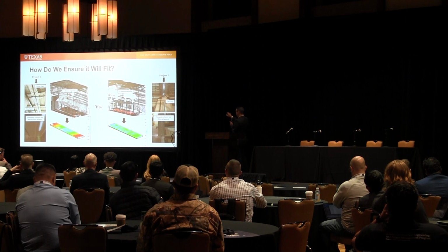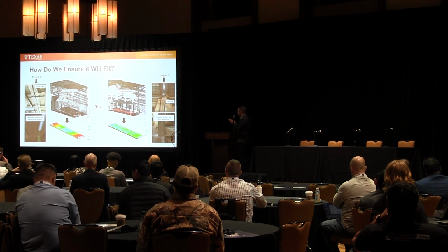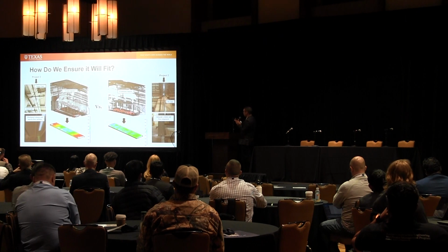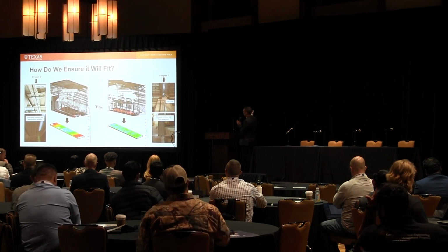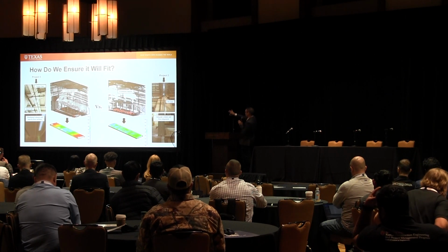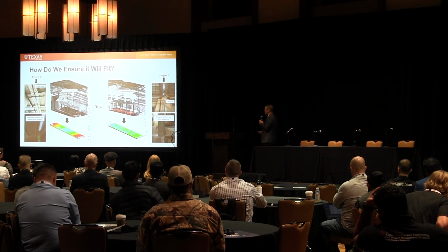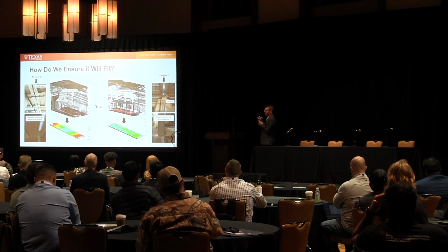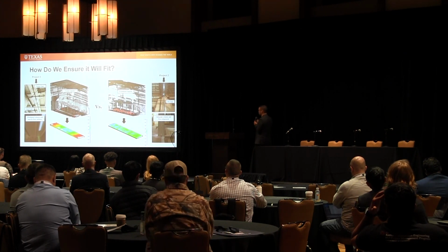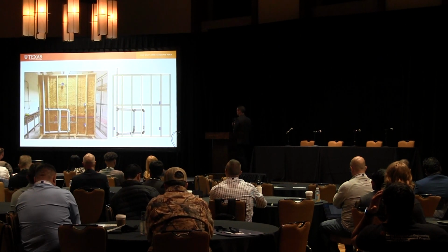The exact same product was being built, but by bringing in controls, in this case, ensuring, just by example here, controlling the flatness of the floor before doing welding, then you guarantee that that geometry is being locked in, is flat, and then that has a ripple effect. Anyways, the moral of this is that you can move from a project with all sorts of geometric fit-up problems to a project where you significantly minimize those. And scanning can really help empower that process.